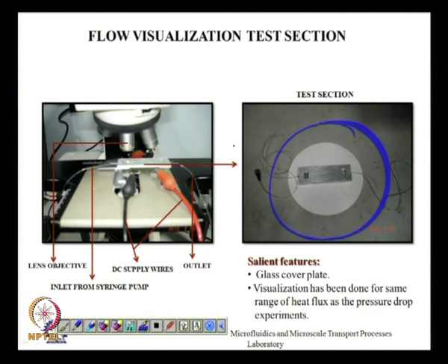We are measuring pressure drop. The flow of liquid is, let us say, in one direction, and we are measuring the pressure drop between these two points, and over here there would be some sort of heater attached, which is going to supply a known heat to the microchannels. So, you have a constant flow, measure the pressure drop, and start adding heat and try to measure the change in the pressure drop with increase in heat.